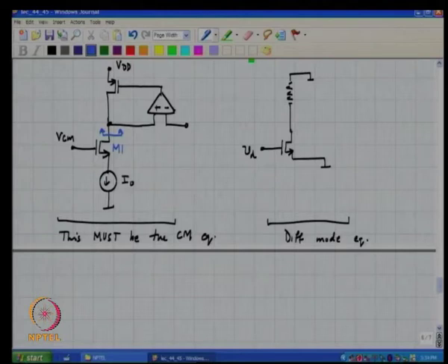if the op amp is ideal, please realize that the potential at this node which was the Vx remains at Vref regardless of whether current is pumped into the node or pulled out of the node, since the voltage at node x does not change in response to currents injected into that node, it behaves like an incremental short circuit, which means that the incremental impedance looking upwards from the drain of M1 is 0, correct.